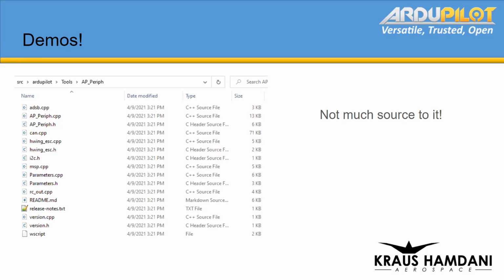Well, if you published MAVLink telemetry down and encapsulated it on UAVCAN, then you could have the OSD in the AP_Periph. Yes, that's one thing that I actually did a couple of years ago: a MAVLink over CAN translator, or rather a tunnel, so that a device on the other end only talked MAVLink, and it just accepted the CAN packets and popped them out as MAVLink.